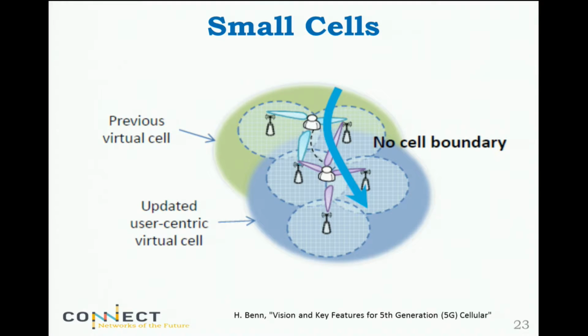So you do design the cell size in a way so that the SNR is good enough at the edge. Here there is, in a sense, no edge. There is no edge problem. It is that the cells are so small that that's not the problem anymore. So the problem is much more of an interference nature. So these are interference limited systems, and it changes the treatment altogether, because if noise is the main factor, then you can do some things.